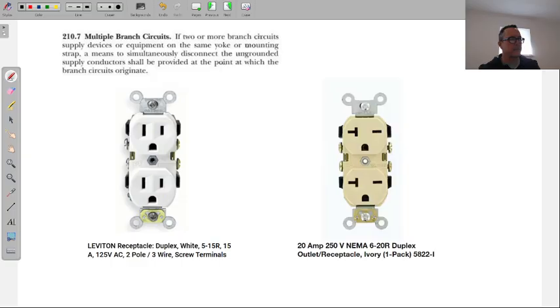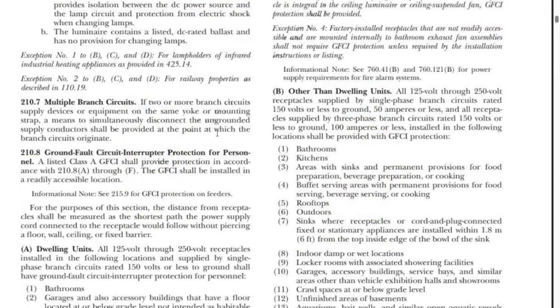All right, so a couple things again, just to keep in mind here. Whenever you're buying receptacles, you're going to want to make sure that their voltage rating is matching what you're wiring up. If you're just wiring up regular receptacles in a house, then 120 is fine. But here's where people make the mistake. You run into Home Depot, you try to grab an outlet for a dishwasher garbage disposal situation, you remember, I'm going to break this tab, no worries. But I want to get the cheapest outlet, so you grab the one that is rated for the lower voltage. And yeah, you can certainly fail an inspection with that. I don't think there's anything damage related. I think the receptacle will be fine, but again, it is a code violation.